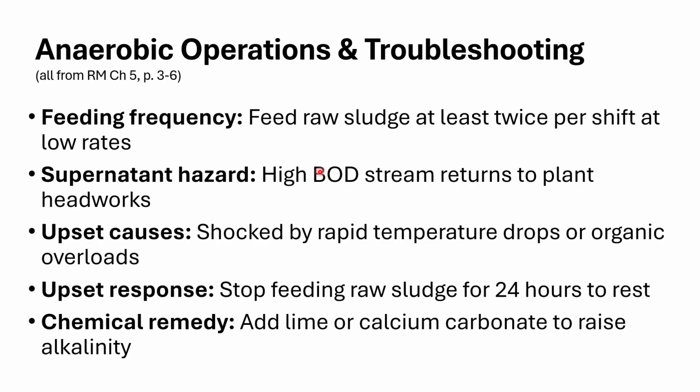So we're sending high BOD and low dissolved oxygen. Didn't write it down here, but it's also got low dissolved oxygen. We're sending that back to the plant headworks. So that's got to be balanced too, because we could cause ourselves a problem by sending too much organic material or BOD out to the headworks and it being oxygen deficient.